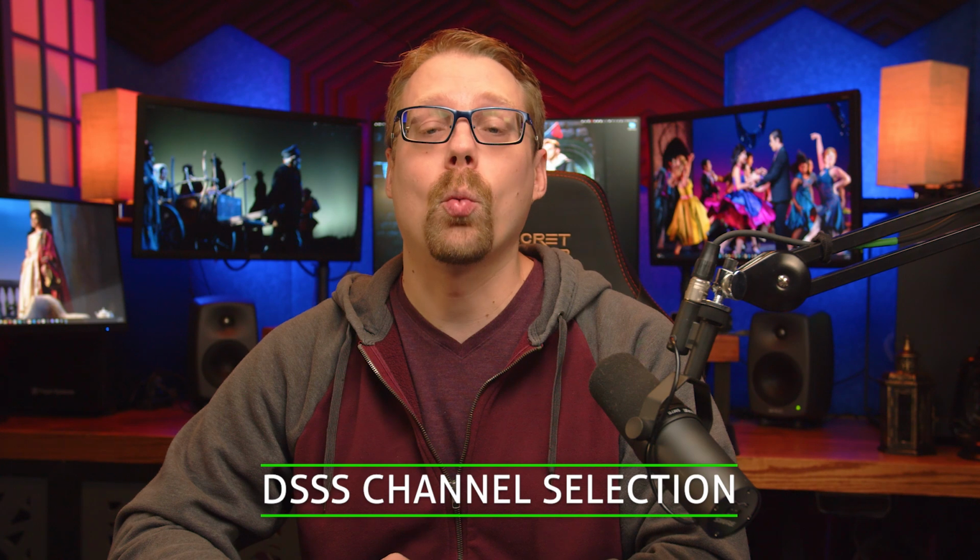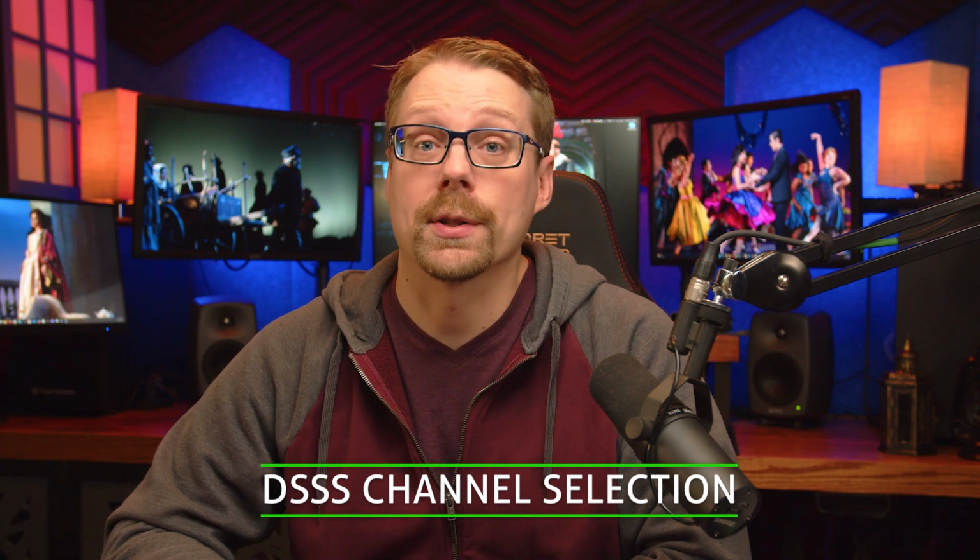In today's tech tip, we're going to talk about how to turn off automatic channel selection and designate which channels your 2.4 GHz units will use. Now, for most customers, automatic channel selection is the way to go, but occasionally you want to be able to select your own channels. We're going to use the RC4 Wireless Commander software in conjunction with an X-Stick or another RC4 Wireless device set in dongle mode.